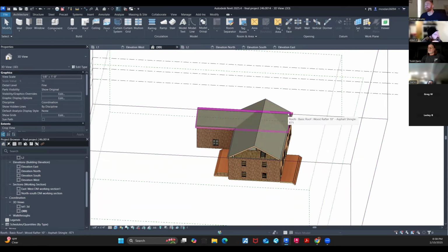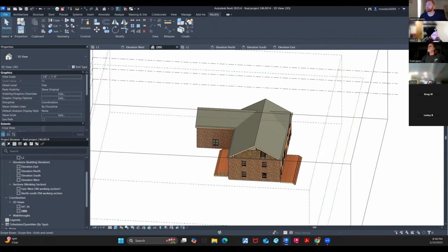So we now want to utilize some tools that are very, very handy. If you go to the modify tab, two over or four to the right from there. Okay, so see if you can find the cope, cut, join commands, all three of those just to your left. Right here. Those are the cope, cut, join. Just to the right of cope, you've got one that looks like a roof.